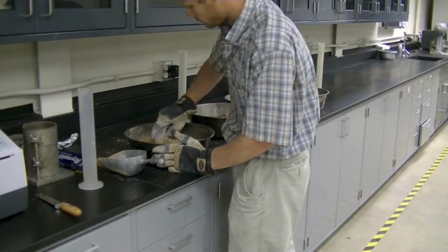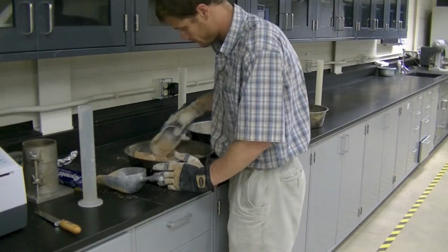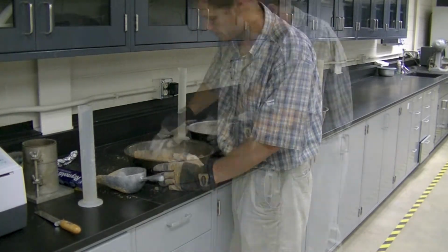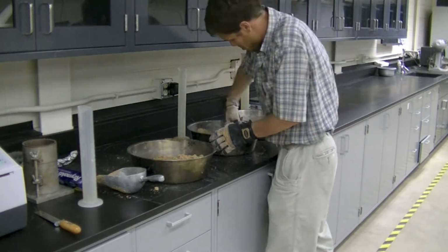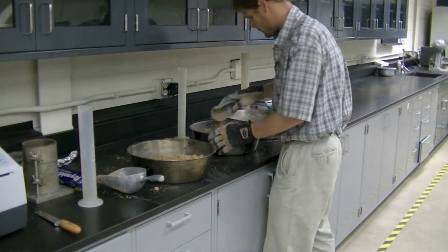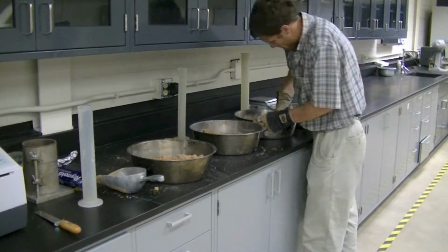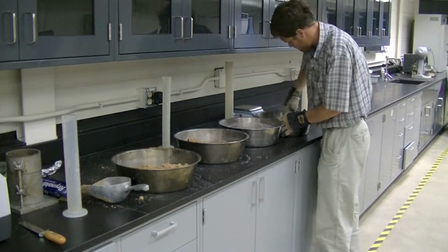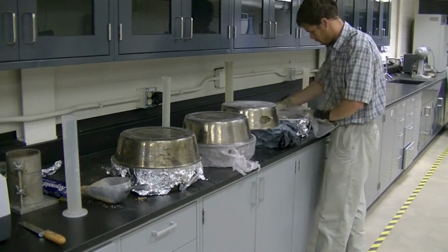Thoroughly mix each subspecimen with a scoop. Do not mix by hand because water can adhere to the palms of the hand, taking away from the moisture content of the subspecimen. Mix until each subspecimen is consistent and has the same color throughout. Refer to Table 2 of the ASTM standard for standing time of moisturized specimens. Since our soil is a well-graded sand with fair amounts of clay, our standing or moisturizing time is 16 hours. Cover the soil adequately and allow soaking to occur for the specified amount of time.